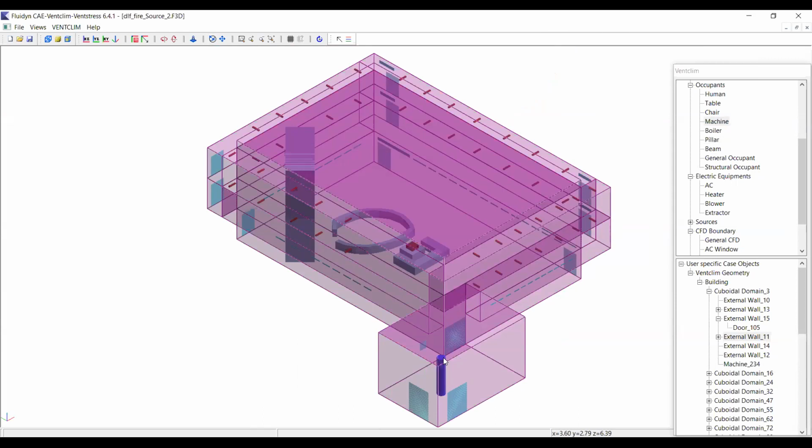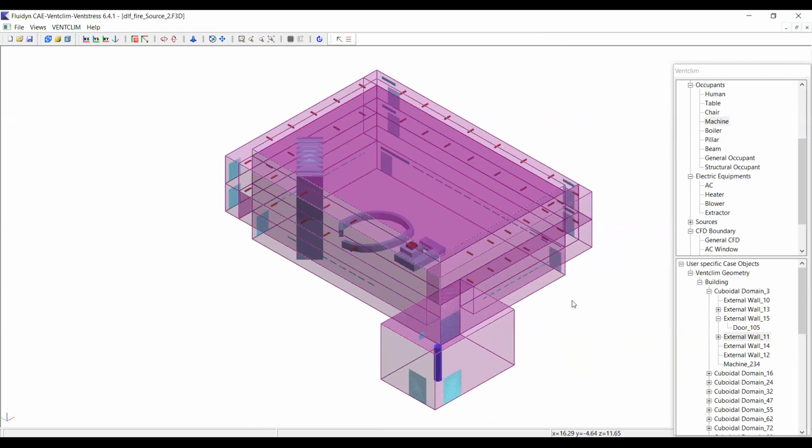Once you load this geometry in the GUI, in this case, it will ask whether it's an open condition, meaning it will ask for the ambient conditions. In this case, it will activate porosity. We can give full porosity like 0, or we can provide partial. If we give 0, the flow cannot pass through this at all, so it's like a blockage.